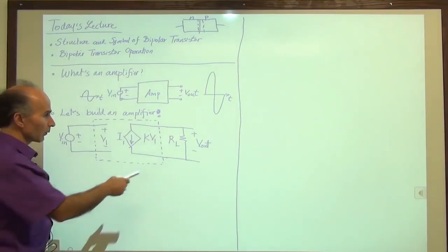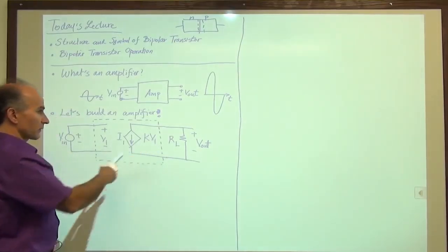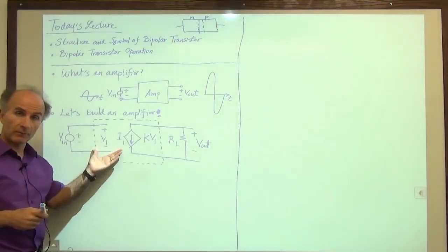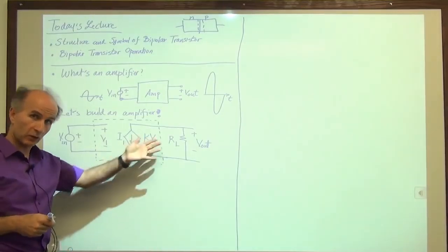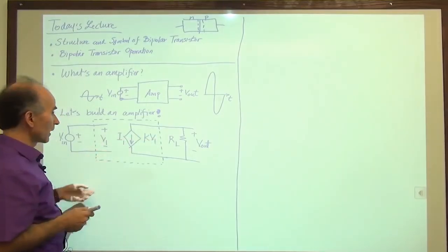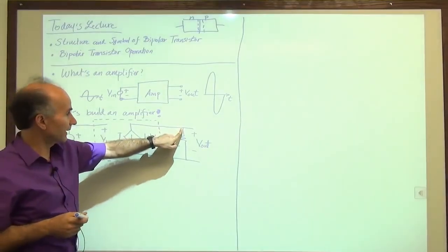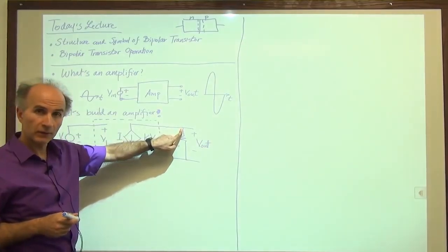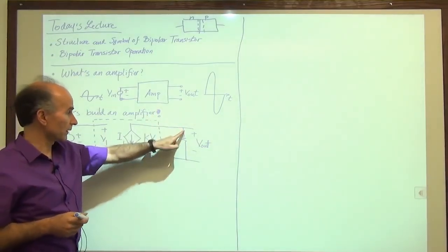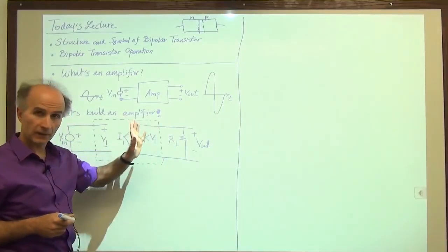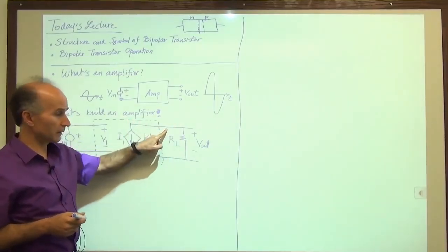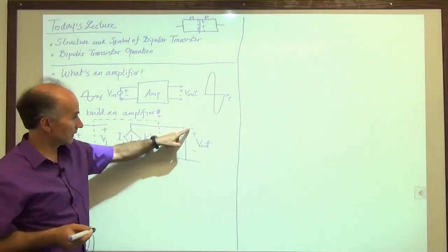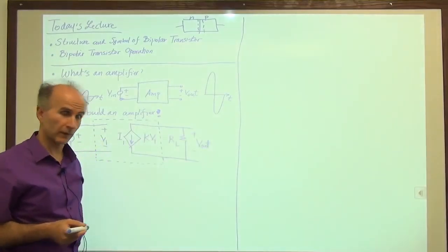Okay, well, how do I analyze the circuit anyway? This is very simple from circuit theory point of view. You have analyzed much more complex circuits. What I will do is write a KCL at this node. I have two currents, this current and nothing else. So this current plus this current has to be 0. This is not going anywhere, so there's no current there.